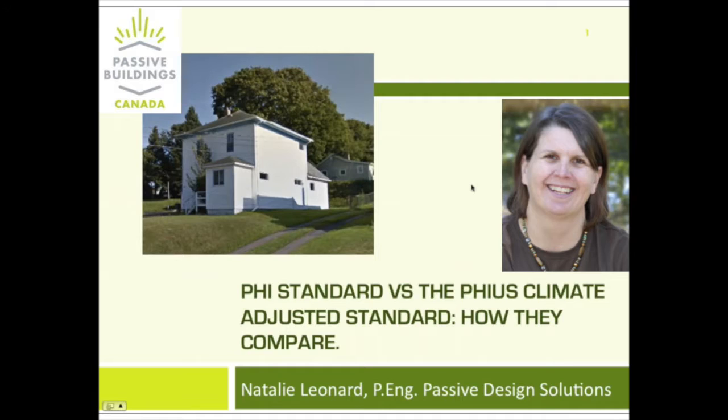Yeah, sure. There's actually a resource on the PHIUS website, somewhere in there under tools and resources, and there's a spreadsheet that PHIUS put together, which has been extremely valuable in making the energy modeling easier, but also in evaluating which units to look at. What they found was that a lot of Canadian HRVs dump the waste heat from inefficient fans into the supply air, thus bumping up the sensible recovery efficiency numbers, but the electrical use is really high.